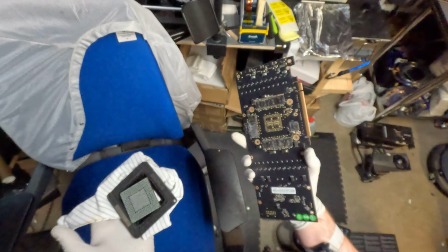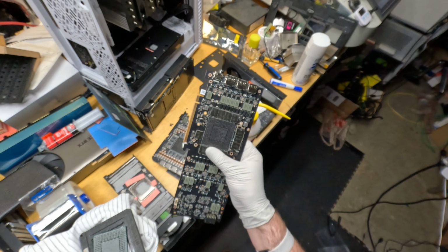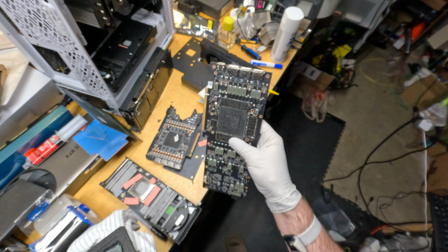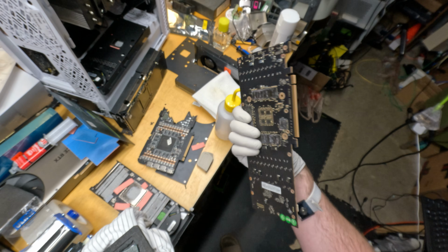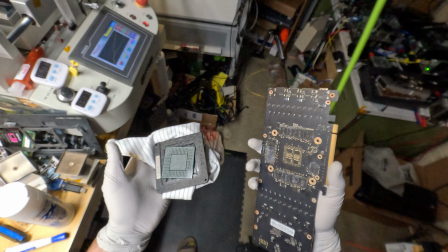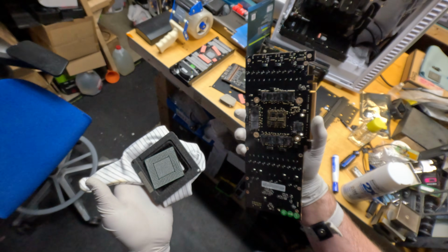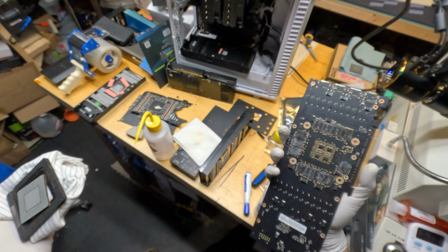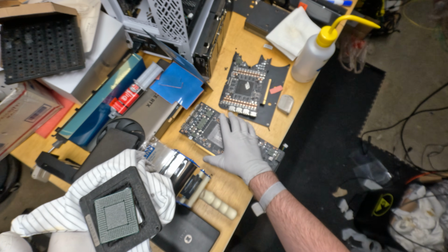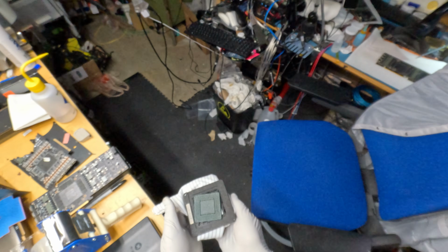So essentially this card, my running theory is that there's something possibly either wrong with the circuit board or one of the memory modules involving the chip select function, where it can address either the front or rear side memory module, because we see an issue when the card goes over 24 gigabytes used on specifically comfyUI WAN 2.2 workloads. I didn't dig into exactly what other workloads would crash it, but I saw on Vulkan on Windows that it didn't crash it. Maybe it's the CUDA version, but I don't know.